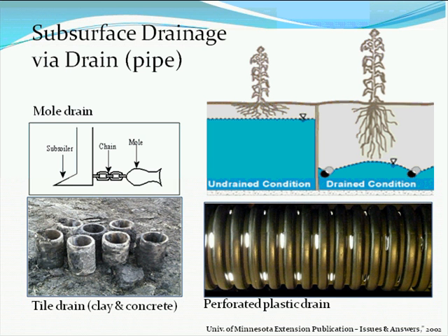The next generation of advances in drainage came with the creation, manufacture of clay and concrete tile drains. These are not perforated, so they're placed next to each other with an inch or less spacing in between to allow water to enter. But most modern drainage systems use perforated corrugated plastic drain tubing. Usually these are 4 to 6 inches in diameter.